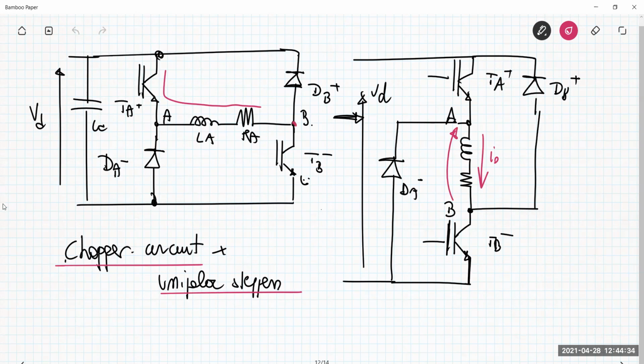Just remaining on this topic, regarding the stepper motor. Remember that when we talked about the stepper motor, I said that we developed some insight for drivers of unipolar stepper motors, because we didn't have all the information we needed at that time for discussing the bipolar stepper motor. Bipolar stepper motors are those specific steppers that can be operated by reversing the direction of the current that flows through the different phases. Remember the previous discussion of the stepper motor. But now we have this possibility.